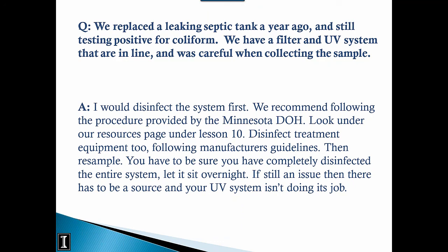And the WQA's email or website is just wqa.org. So once you've done all that, you let it sit overnight so that there's chlorine in the lines and through all the taps and the shower heads and toilets and everything else. Then flush everything or get all the chlorine out of there, and then you should be able to resample. And it should not have anything in it.